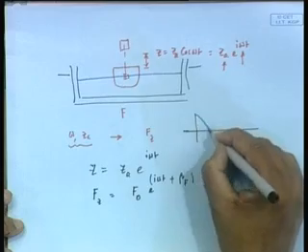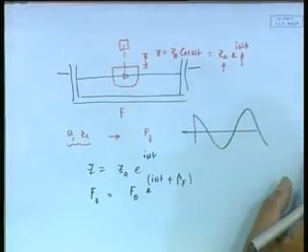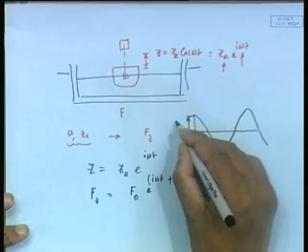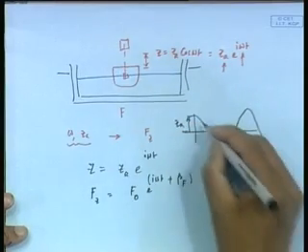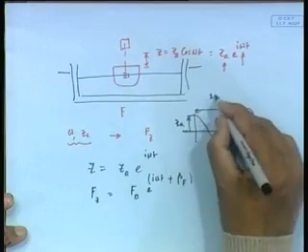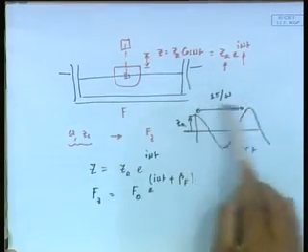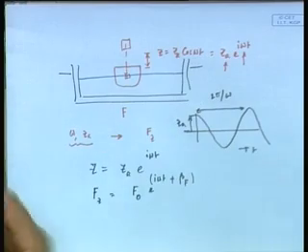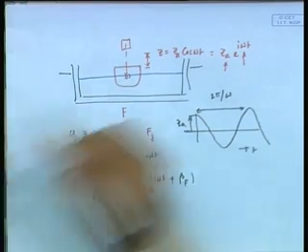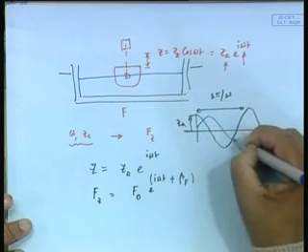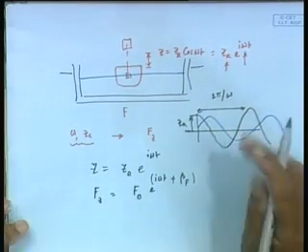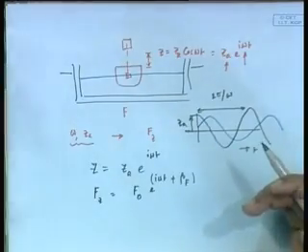Because remember, how I get this beta f, I have oscillated that, oscillation is this is what I have given, right, input data. This is my ZA, if this is my period T, this is my 2 pi by omega, agreed. See, I have oscillated that, so I know of course ZA, period 2 pi by omega, etc. What did I measure? The force history. Remember history. So force looks something like this. This is the output. This is what I have measured. The equipment has measured this force, that every second I plot.